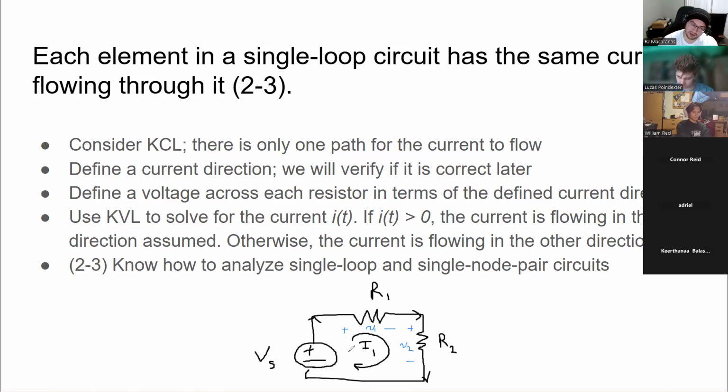We'll get into this a little bit more, but the sum V1 plus V2 must equal VS, right? Because if I start here and take this path, I go up VS, so up here I'm at VS. Then if I traverse through this path, I go up V2, I go up V1, and I arrive at this VS. So VS is actually equal to V1 plus V2. But anyways, that's a single loop circuit.